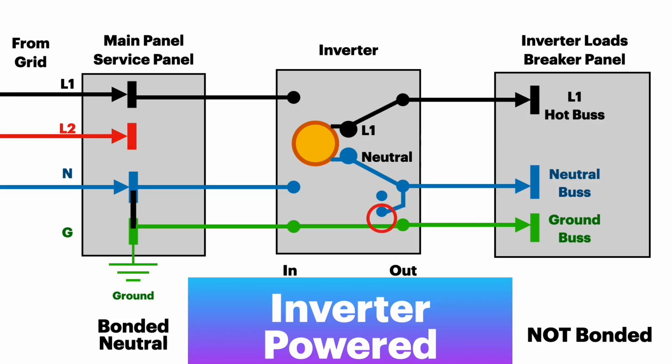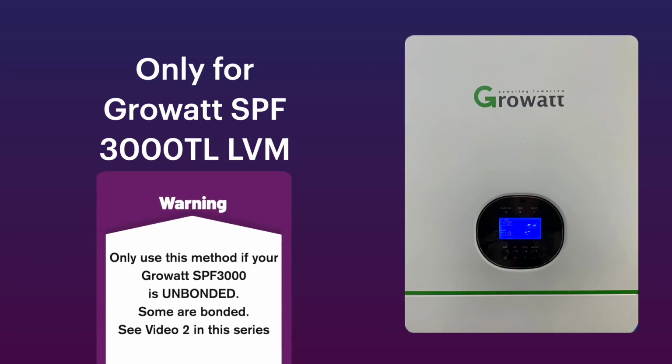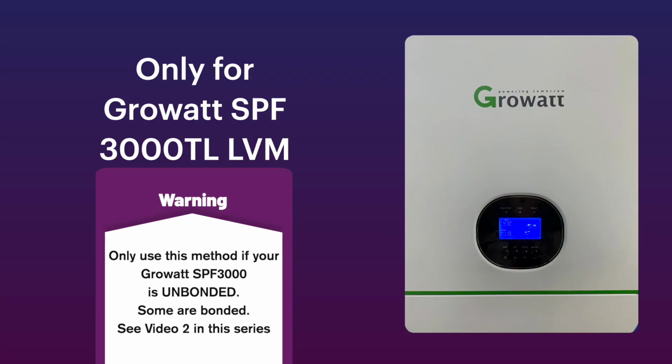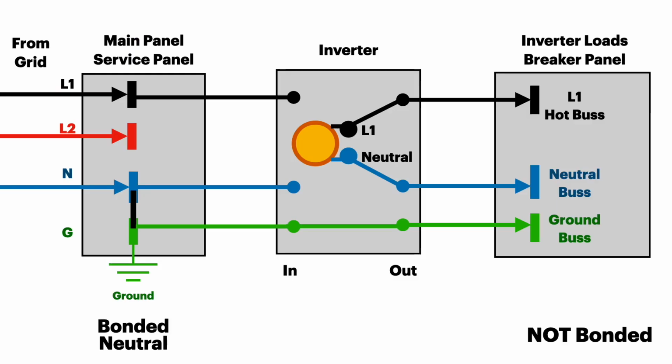One way to make this system work, unfortunately, only applies to the Growatt SPF 3000. You only use this method if your Growatt is unbonded. Some of them are bonded. See video 2 in this series to find out how to test your Growatt and see if it's bonded or not. If it's unbonded, Growatt says you can do this.